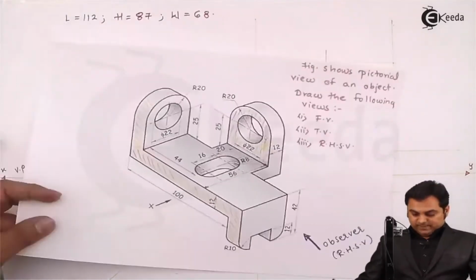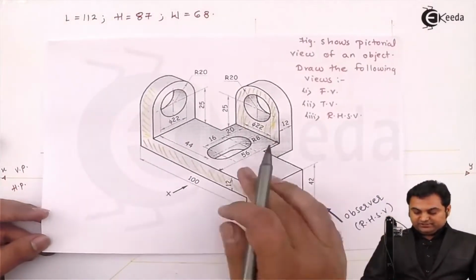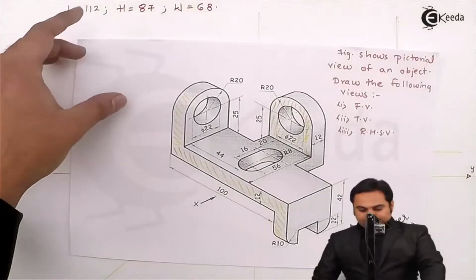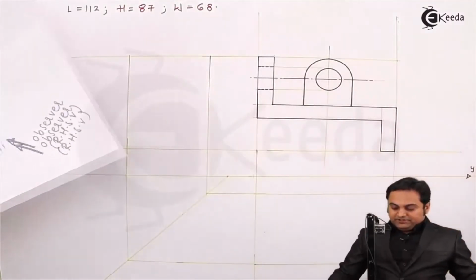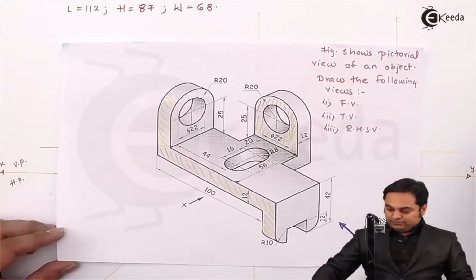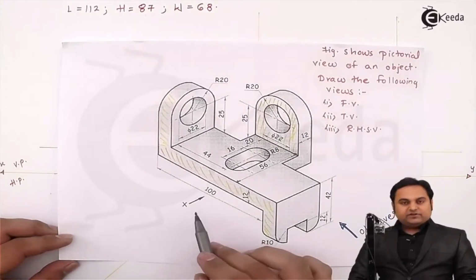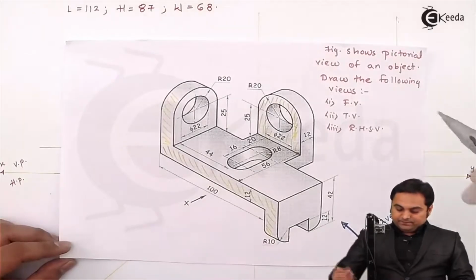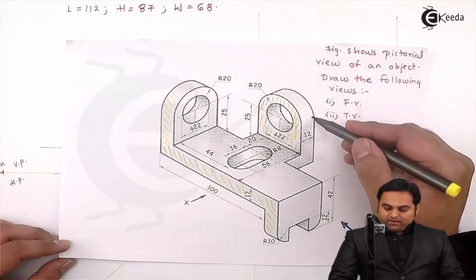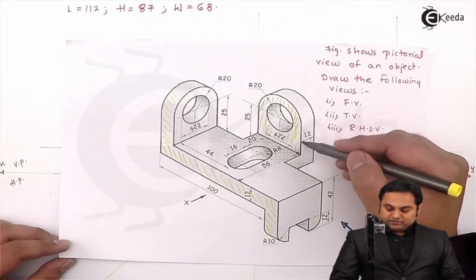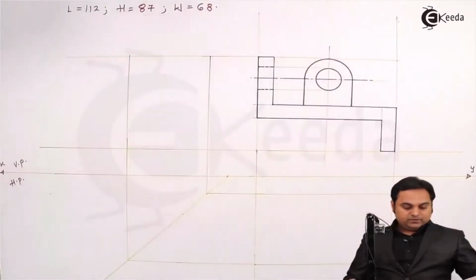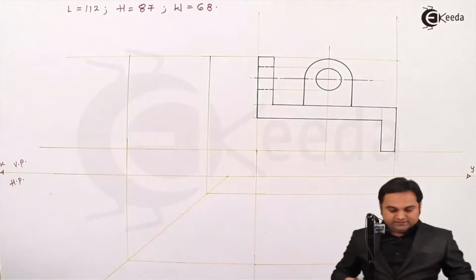Next, after that, there is another portion which is hidden, which will not be seen from the front. So here I have completed the visible part, and for the hidden portion, if we look into the diagram, then from the front, that is along x direction, this line which is behind is not visible, but a certain part of it is coinciding with this line. So the remaining portion in this block should be hidden. So that same line, I'll project it light.